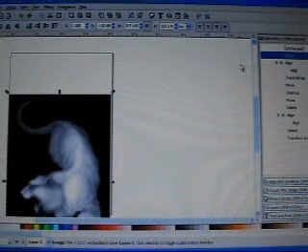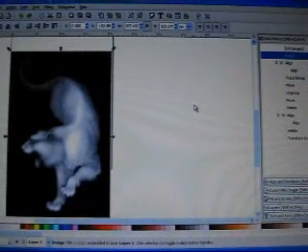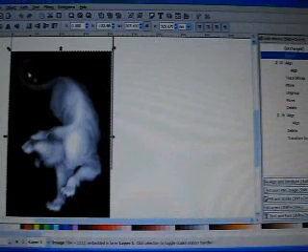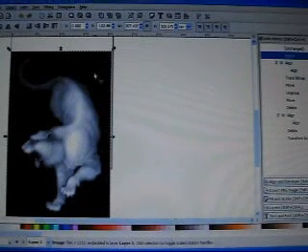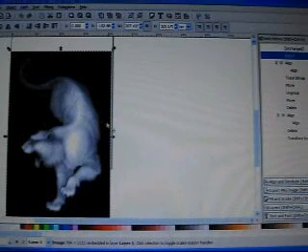Okay, so here we are in Inkscape, and the reason for this is we are going to prepare this image for machining. The plan is to machine this black area with a 1/4" bit, and then come back here with the 1/8" ball tool and do this embossed tiger. So I'm going to use a flat end mill 1/4" to cut all this black material away first, and then I'm going to come back and cut this embossed thing. So I'm going to use Inkscape to do that.